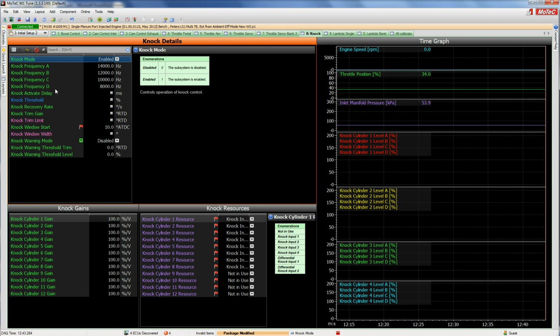We're looking for a frequency that shows the most noise for NOC, or sorry, the most signal for NOC and the least signal for noise. It's called noise to signal ratio. So there's not always a guaranteed known frequency for any given engine. Most of the time, if you've got no idea, you should start around the numbers I've given you there. And in fact, the default is pretty much 10 to 12. It will get probably 60% of the engines out there today.